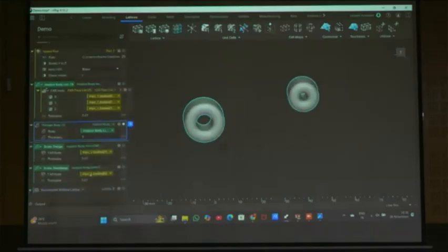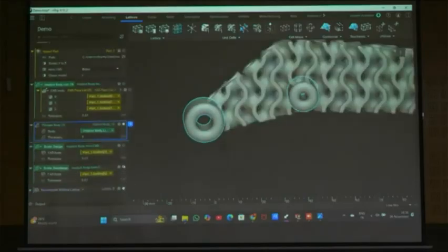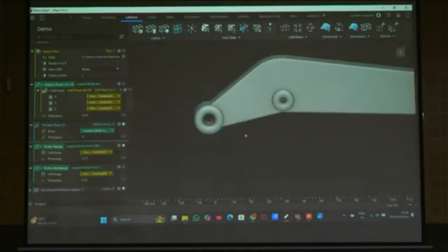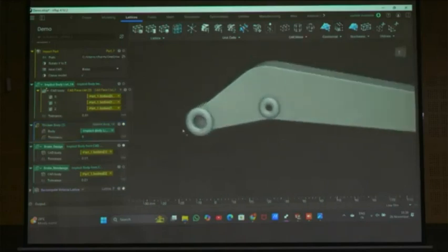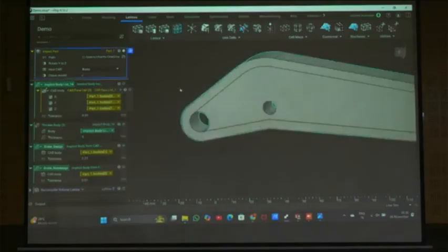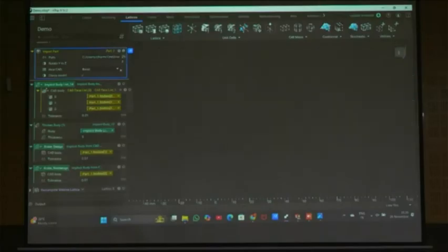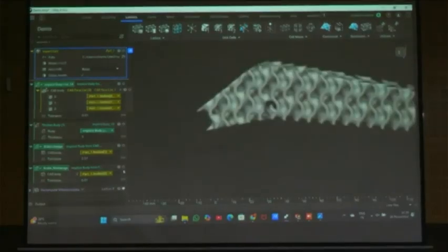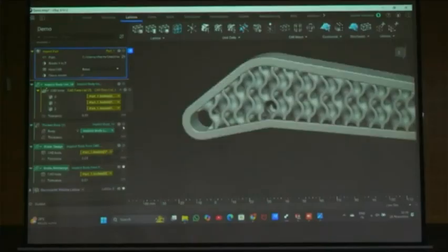Wait, we will see now. Design, right? Are we getting like this? See, this is the original design. This is the one we are getting, but the hole is not proper. So here we need to apply the intersect. Intersect means it will find the common body. So that we can find it. So Boolean intersect.